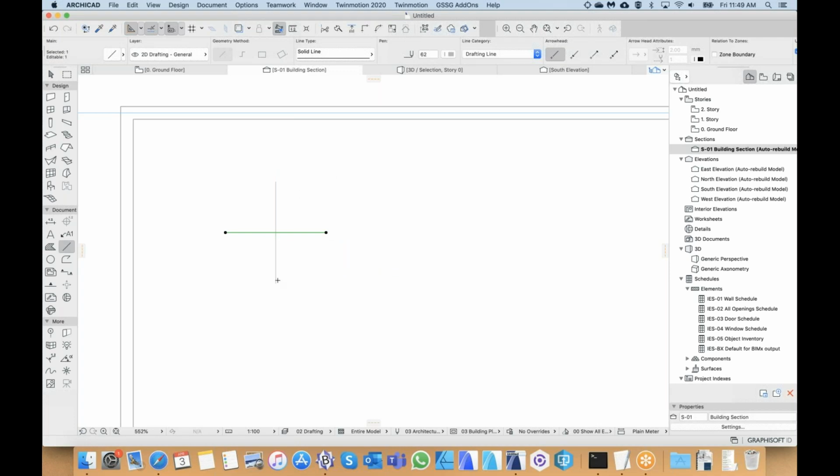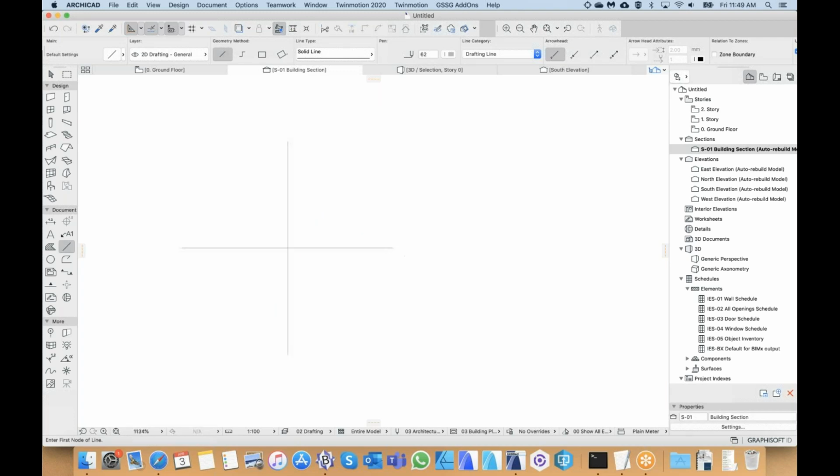Mirror will work as well, I just find rotate a little easier, because with mirror you'd have to find a diagonal instead. So: Control E, tap Control to make the little plus appear on my cursor, choose the center point, then choose one axis and rotate around to the other axis. Now I've got two lines, and they're intersecting.